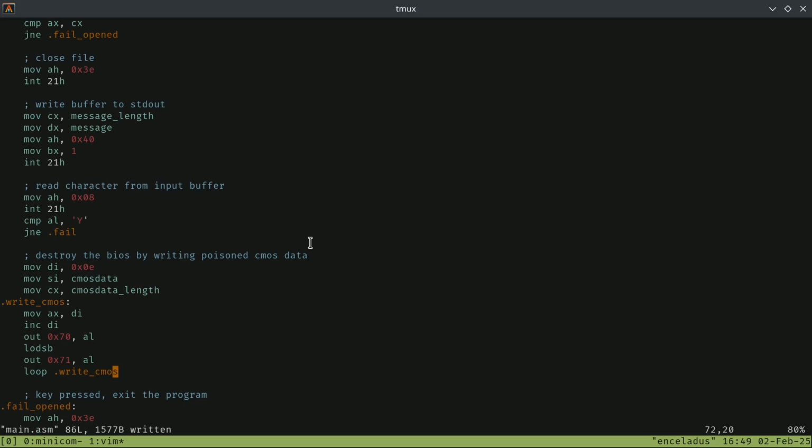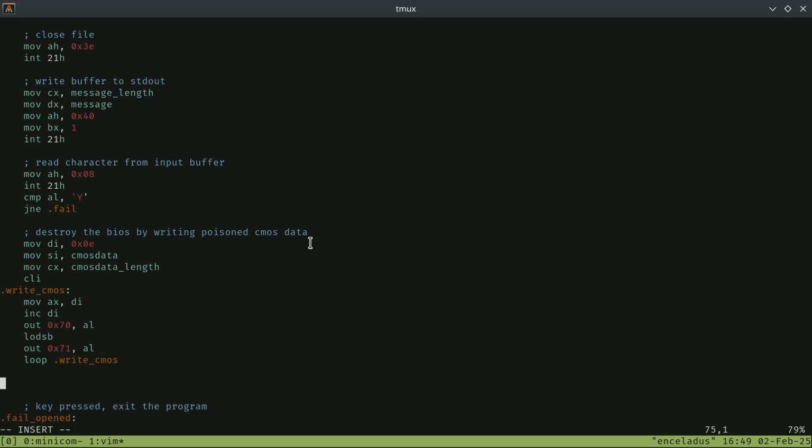So we can use it to repeat a section of code a specific number of times without having to check a loop counter. As DOS might attempt to modify the contents of the RTC inside of an interrupt handler, we need to ensure that no interrupts will run while updating the RTC. So before the loop starts, add a CLI instruction to disable interrupts. So at this point, we've effectively put the system into an unstable state, so realistically the only thing we should do now is cause the board to reset.